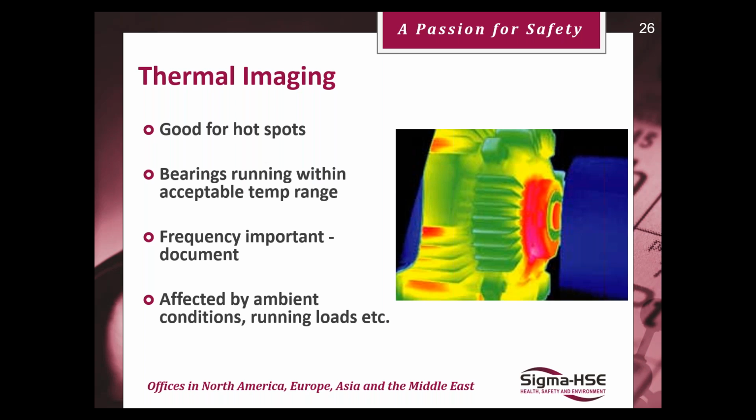So these are the benefits of thermal imaging undertaken for your motors. It gives a good indication if something's about to go to failure, and failure could imply a potential ignition source being created, for example if the motor overruns. This is one of the benefits of undertaking this.